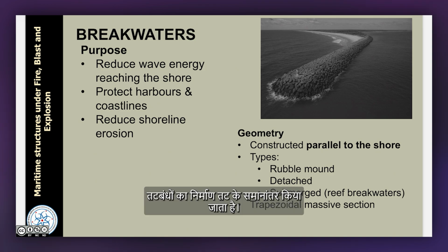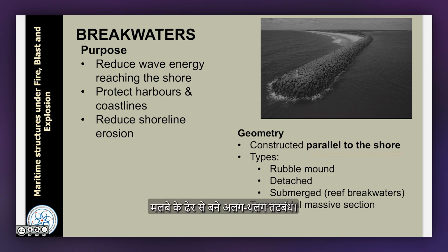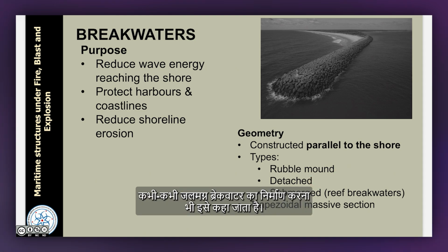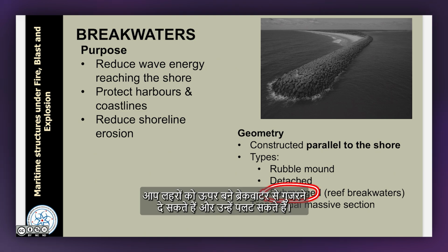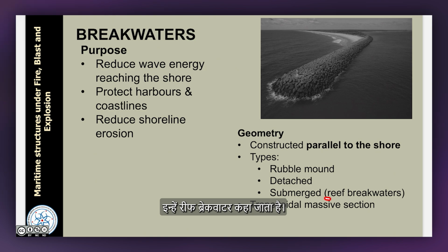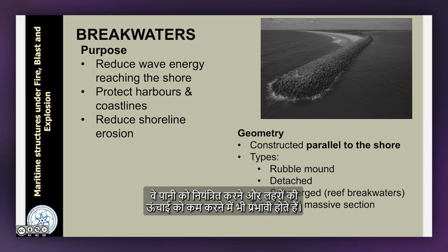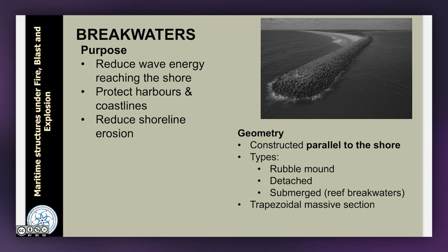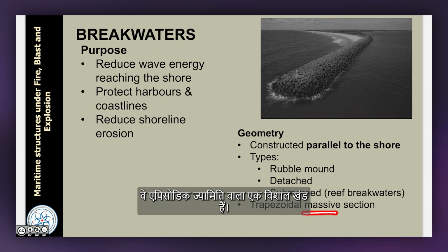Breakwaters are constructed parallel to the shore, as rubble mounded, detached breakwaters. Sometimes one can also construct submerged breakwaters. You can allow the waves to pass over the breakwater and topple them, these are called reef breakwaters. They also are effective in controlling or breaking the wave height. They are a massive section with trapezoidal geometry.